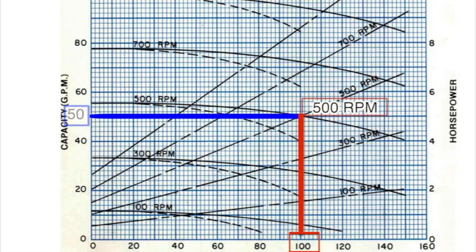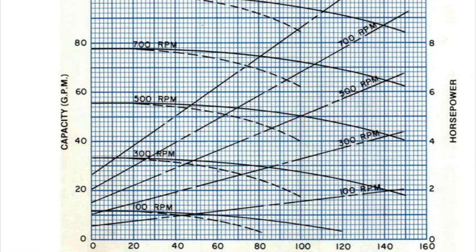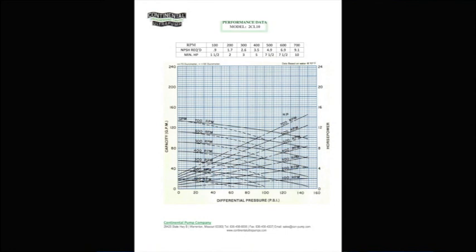So right away, from the start, we thought a 2CL8 was the proper pump for this application. But by using the charts and the information that we provided, you find out real quick that this is not going to work. So we're going to have to go up to the next pump size, and that's going to be a 2CL10. And we're basically going to do the exact same thing.